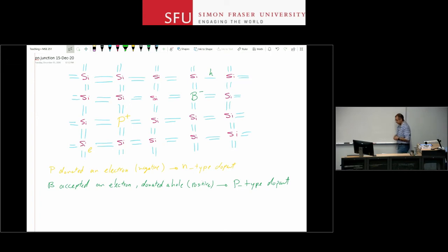They can recombine. And in this case, your net resistivity doesn't really change. So I usually use one or the other, right? I use N-type dopants to reduce my resistivity, or I use P-type dopants to reduce the resistivity. I don't usually use both at the same time.